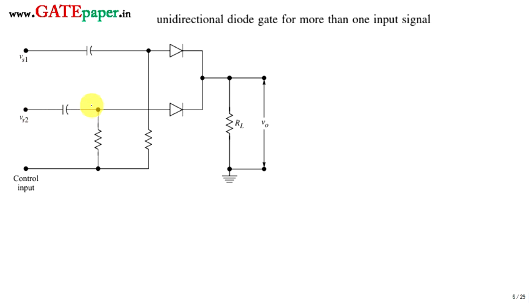They are coupled to the diode P side using capacitors, and the control signal is applied through separate resistors R and R. This is capacitor C and C, this is diode 1 and diode 2. Since you are applying the same control signal, which is rectangular in nature, it may be at V2 and V1 levels. When Vc is at the V1 level, that is the transmission period.